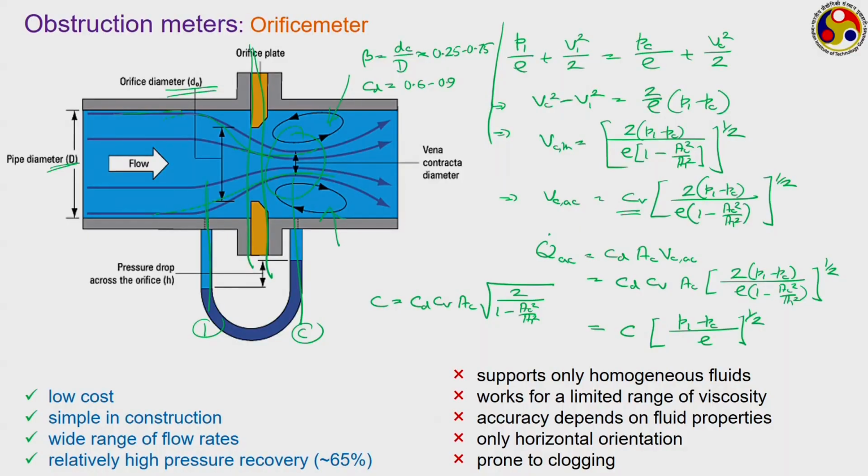Everything looks quite good as long as you are sticking to a general fluid and with moderate level of velocities, but the biggest challenge is to know the position of this vena contracta, because that is strongly dependent upon the channel configuration, on the fluid itself, and even for a given fluid on the flow velocities.